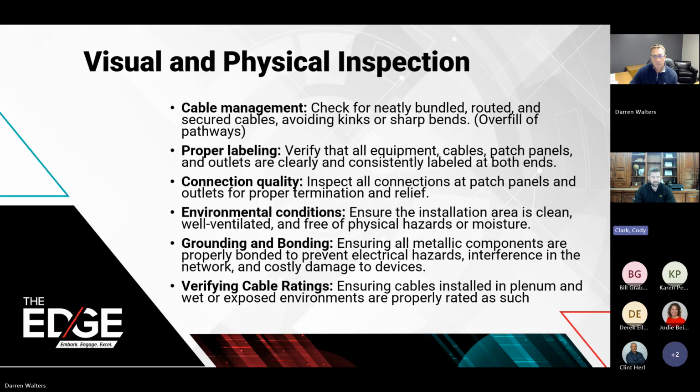That's not just from making sure that the product performs as it should. It's also a code requirement. So if you're in a plenum rated airspace, you have to have a plenum rated cable. Otherwise, you're against code, and the inspectors are going to make you replace it.